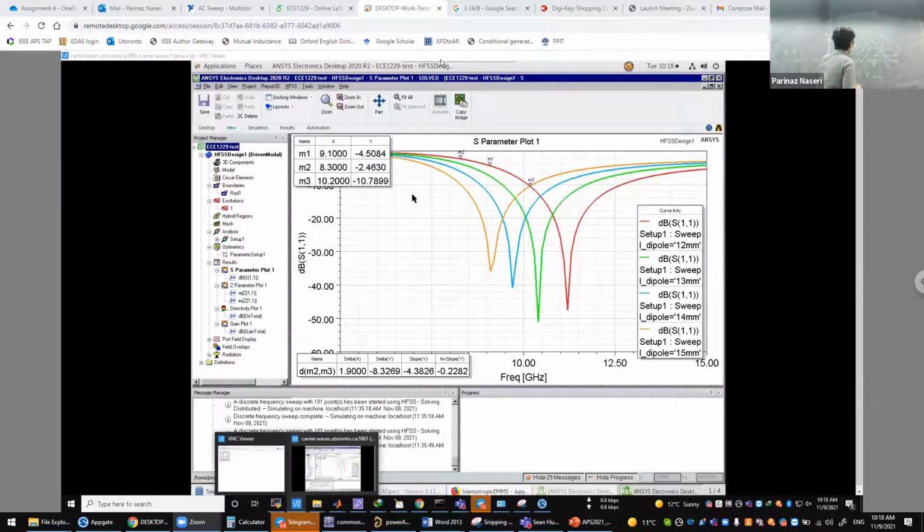Okay, and that's why if you connect the microstrip line directly to the patch, this is not going to give you a good answer. Usually there are some papers that you would read for your project where you have to make some adjustments to the structure of the patch to make this 50 ohm. But anyway, a very simple single layer structure for the patch would be feeding it with a microstrip line. And then in the bottom we have ground. In the bottom we have a PEC, so that no radiation goes in the back. We want all the radiation to go to the front.